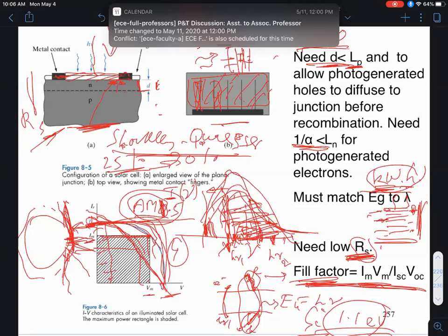The other important parameter is the absorption length, 1 over alpha. When the light is absorbed, we saw in chapter 4, it dies down as I naught e to the power minus alpha L, where L is the distance. So it dies down exponentially. If you have a large absorption coefficient, it will die down rapidly. A short absorption coefficient will die down more gently, okay?